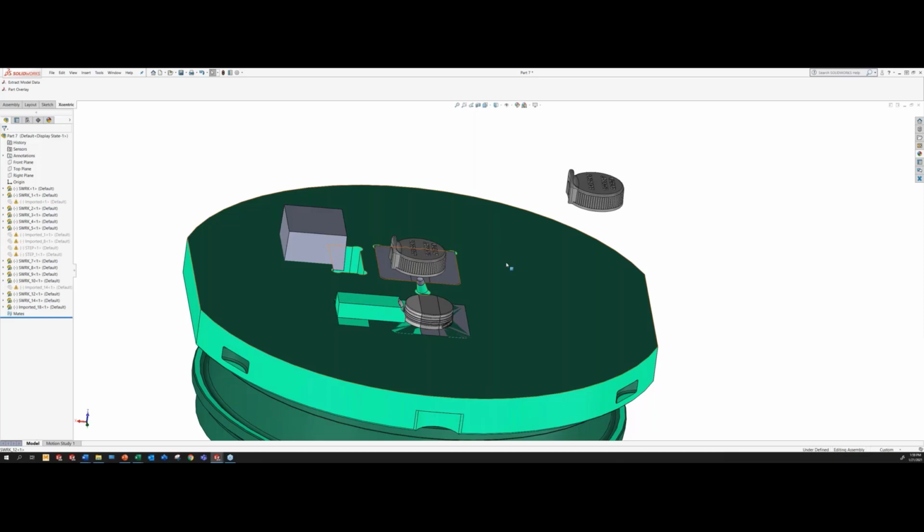If the material comes in its natural state, which most do, you can get it colored to any material. You can add a salt and pepper or have it pre-colored, where they'll just take it and dye it right at the machine that's making it. There are some materials that have set colors that they offer. Something like a Lustran 348 comes in a couple different colors. You've got the natural white, black. I think there might be a red. So if the material isn't black and it comes in some sort of natural variation of it, it can be colored. Okay.